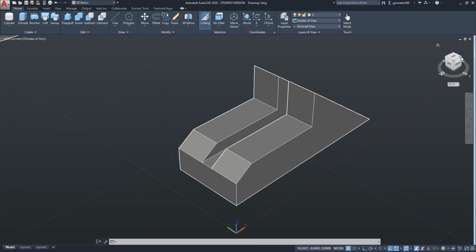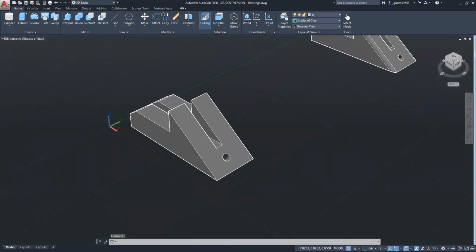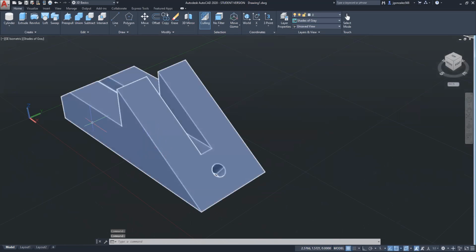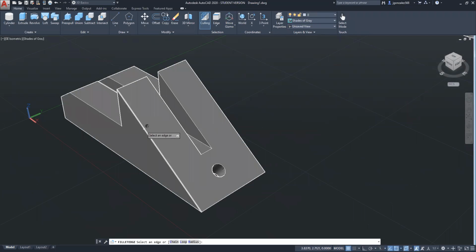All right, now let's smooth out the front edge using the fillet. Let's practice the fillet. So this 3D fillet is right here. So it's the same deal. It's going to want an edge, but you got to give it a radius instead of a distance. So similar, but a little bit different. So click radius, choose, let's see here, 0.25, enter, and